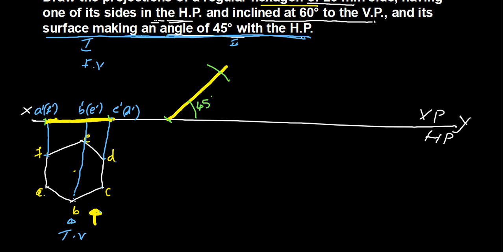Now similarly you copy the letterings also, like A dash, F dash, and whatever distance you obtain, again mark the same thing on this line. So it will be B dash, E dash, and at the end you will get C dash, D dash. Okay, so these are the 3 points on the 45 degree inclination. So this becomes the inclination at 45 degrees. Again draw vertical lines, you have to make projection lines now. Take all these points below with thin lines.